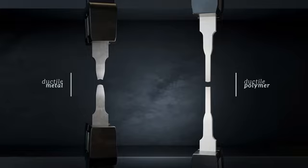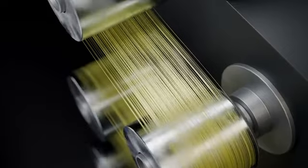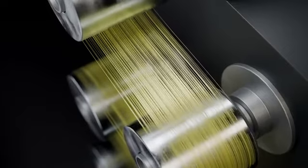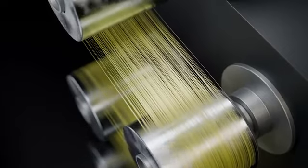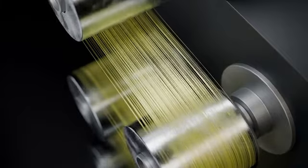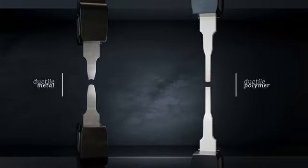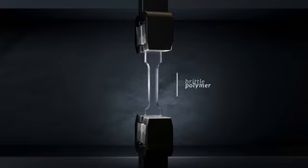This cold drawing behavior is sometimes used to intentionally strengthen polymers. Kevlar is a polymer made of fibers that are mechanically drawn to align their polymer chains, resulting in a material with exceptional tensile strength along the fiber axis. Unlike ductile polymers, brittle polymers fail with very little plastic deformation. Instead of stretching, they fracture suddenly at low strains.